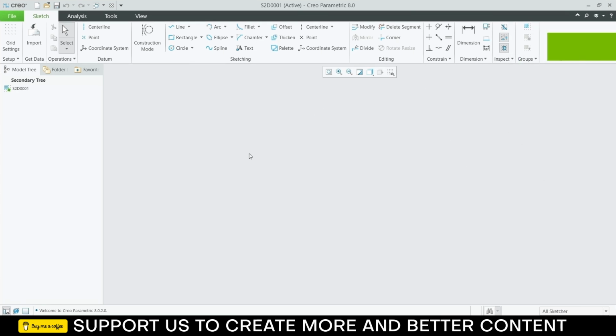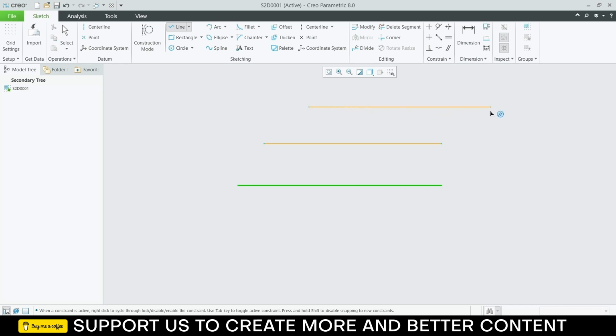Now let's try to understand how things work in Pro. Suppose I want to draw a line. So if I click on it and draw a line, you can see I draw a line. But suppose I just want to draw a single line and I want to end this command. So there are two ways to do it. You can press escape to do this, or draw the line and press the middle mouse button. Just so you know, in case you have a laptop and you are trying to do it on it, it will not work. I assume that you all guys have a mouse and there is a middle mouse button. So by pressing that, you can end this command.